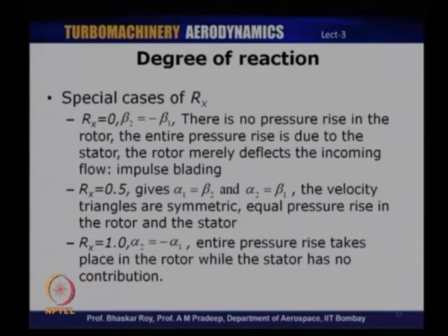That is, in this particular configuration, if degree of reaction is 0, the rotor primarily does not do any work on the flow, it simply deflects the flow. Entire pressure rise takes place in the stator.